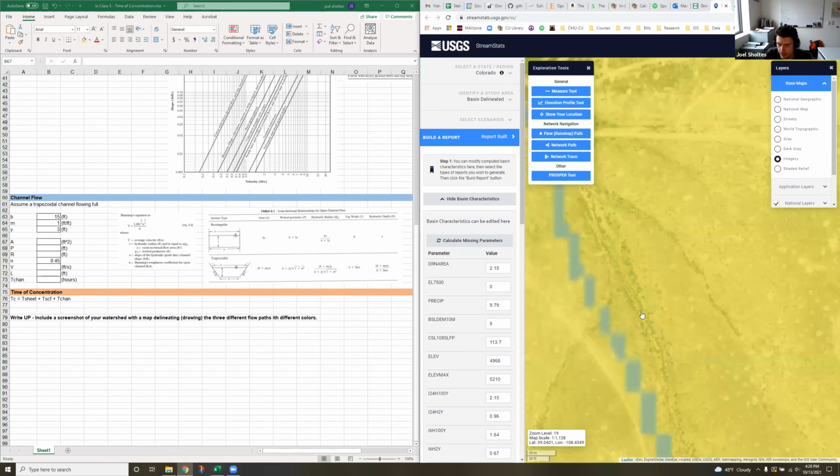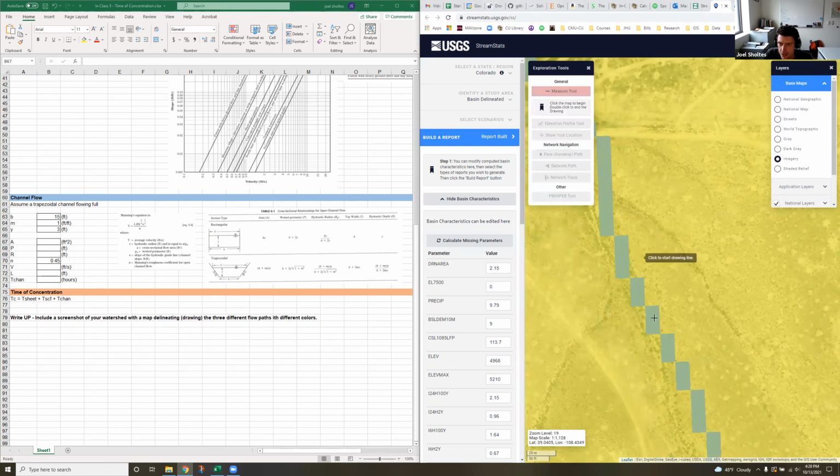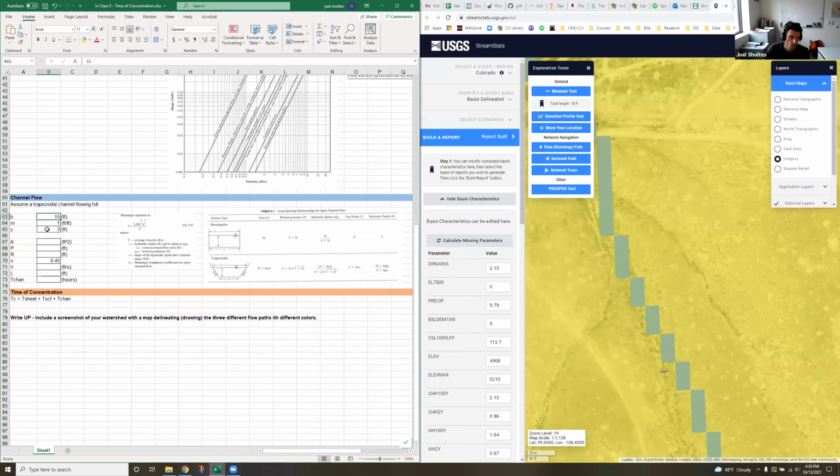Let's go ahead and zoom in. We can pick a midpoint in the valley, and we can measure the width of the channel. I'm not zooming in super well. You might go to Google Maps and try to do this, but we'll try to get a rough width. This is a wash type of channel, so maybe somewhere around 15 to 20 feet. Then we can use that for the width. Again, you might go out in the field to actually measure these things, but we'll say that the depth is somewhere between 3 and 5 feet. And then we'll assume a one-to-one slope for the valley margins.